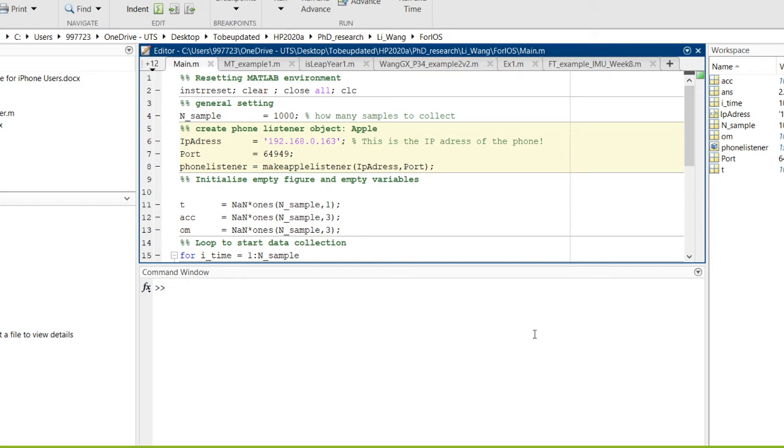Last time I mentioned that you cannot generate a movement over 30 or 35 hertz. Even 10 hertz is difficult to generate, if you try. In that case, we design a low pass filter at 10 hertz. But fortunately, for this one, we do not need to design the filter to get rid of 10 hertz. You know why? Does any group understand why? Because our sampling frequency is only 20 hertz.